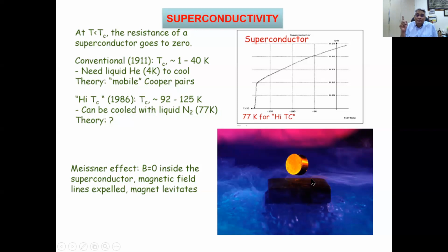And I also said that problem, the current density, which is 10 raised to 2 amperes per centimeter square, shoots up by almost 4 orders more, becomes 10 raised to 6 amperes per centimeter square, if the same polycrystalline yttrium barium copper oxide is obtained in the form of a single crystal or a thin film, right? 4 orders of difference in the current carrying capability.